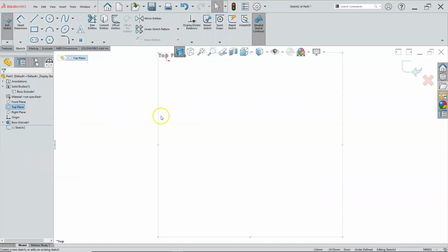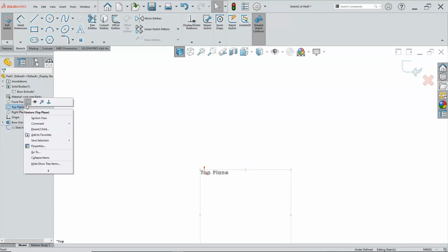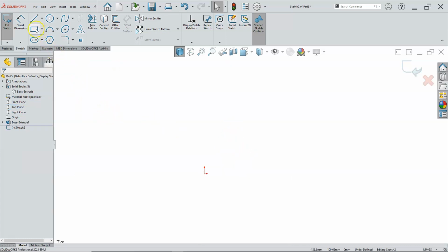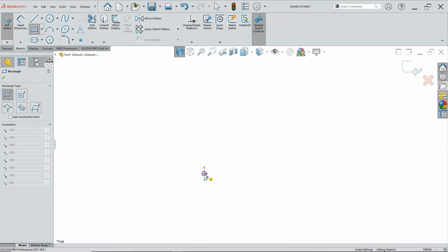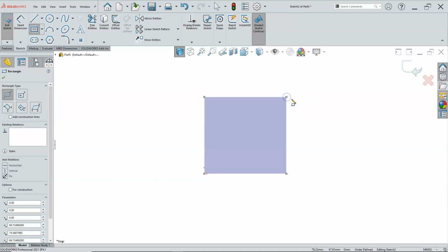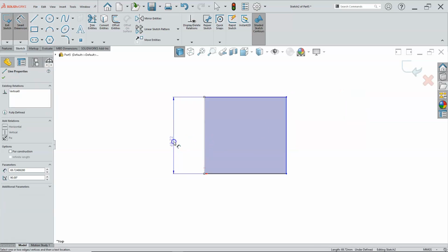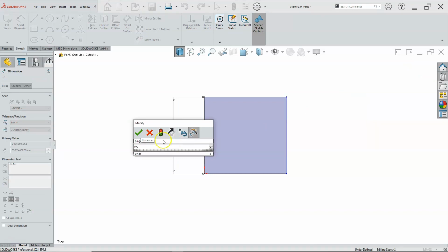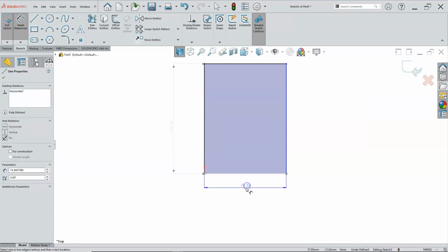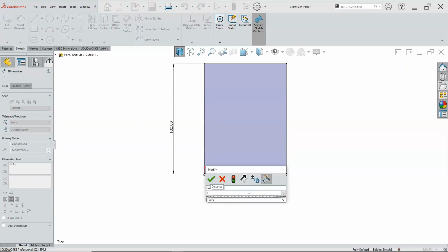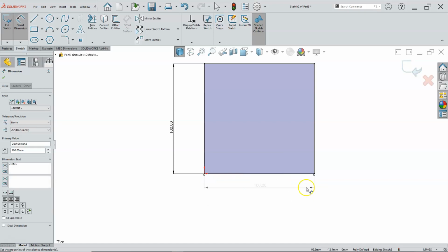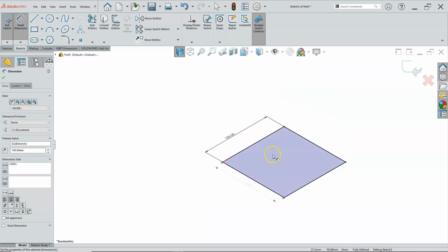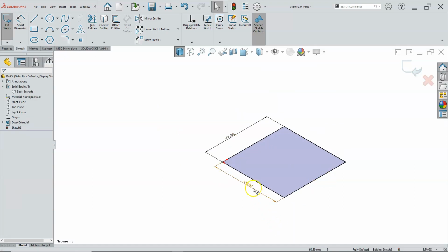If I go back into the top and open a sketch, again my force of habit is to right-click and go into the sketch. Then we will look for that coincident, drag out some distance. Maybe this one can be 100. And my design intent, this one may grow, so I'm not sure in what ways. So we'll go ahead and set those dimensions independent rather than equal.